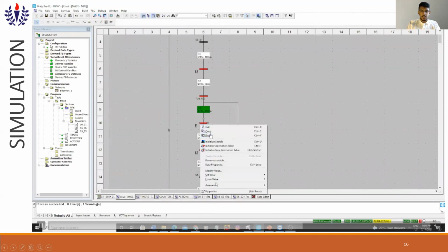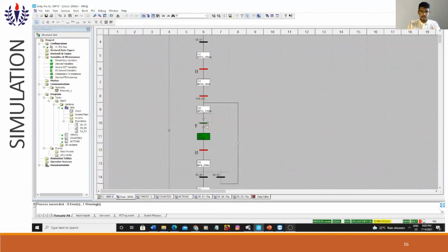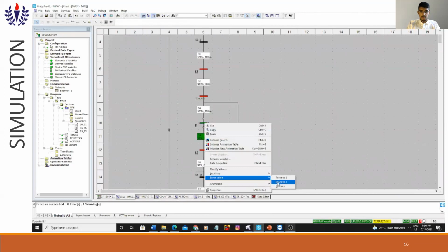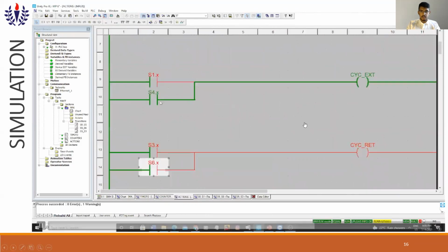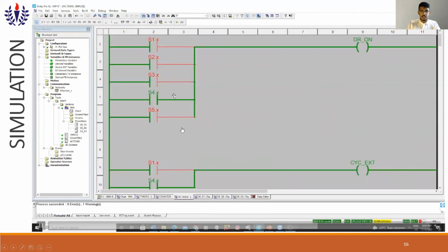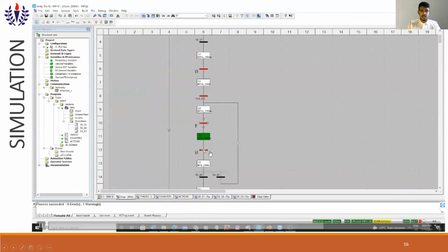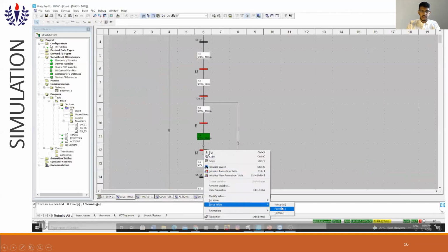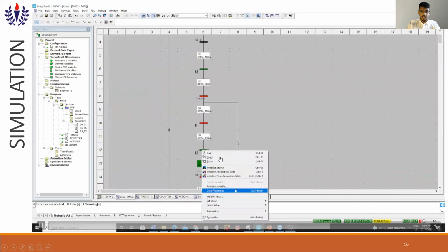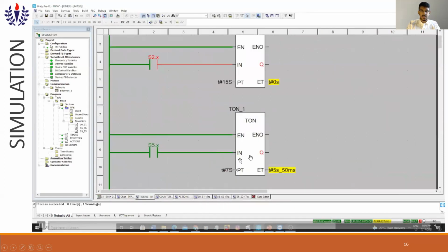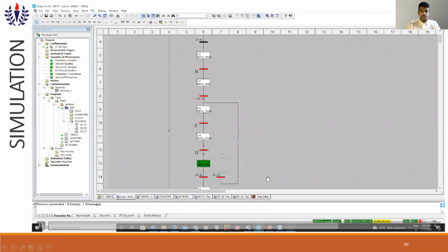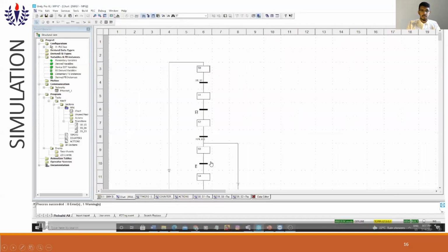Once it reaches the intermediate position, it moves on to S4, where it is going to extend, and the drilling machine is going to be on. Once it reaches the lowest position and drills again, as we had mentioned in the previous step, it's going to drill for 7 seconds. Once the 7 seconds is completed, as you see here, now it comes out of the loop.